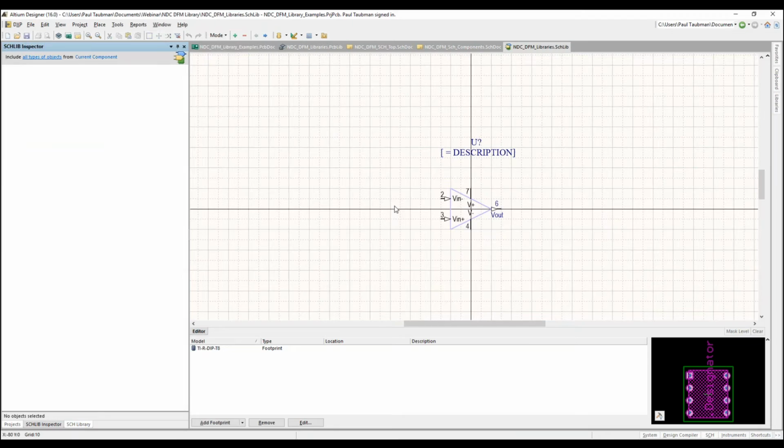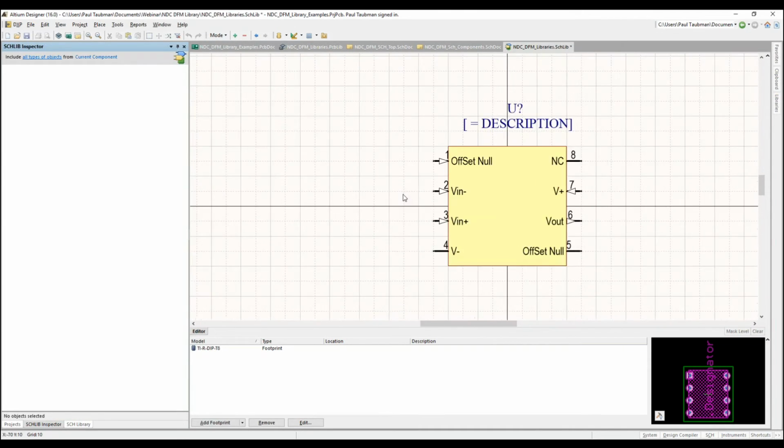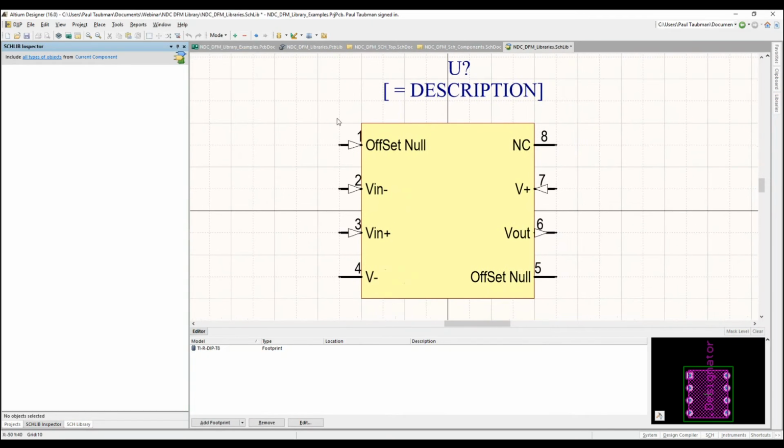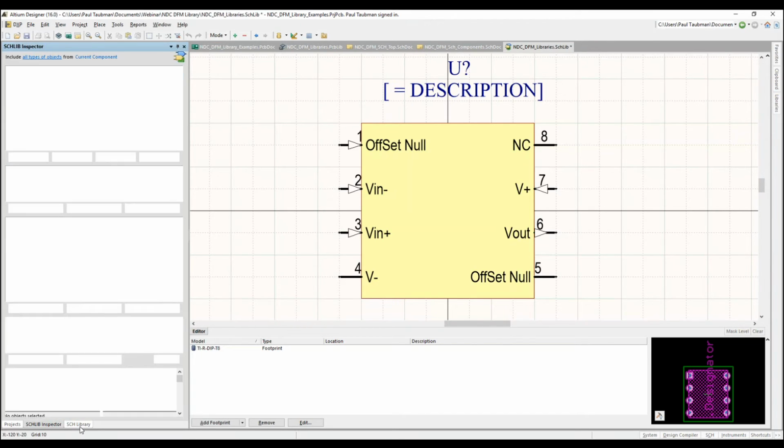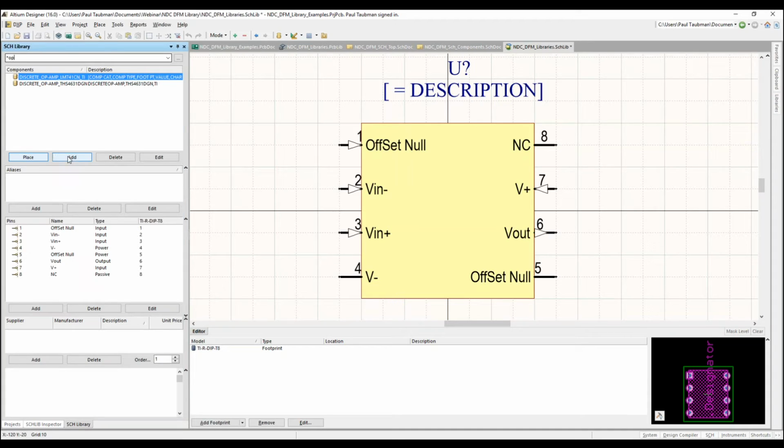Now, you may say, great, that's awesome. We're done with the graphical part, but there's a problem. And it's something that you've got to be very aware of. Altium is very particular about its alternate views. And if you have a certain number of pins and their naming that are different from the different alternate views, especially the pin numbers, it's going to cause big problems. In fact, it was one of the cases I first did many years ago. I started at Altium. It took me 45 minutes because I had no clue what an alternate view was all about.